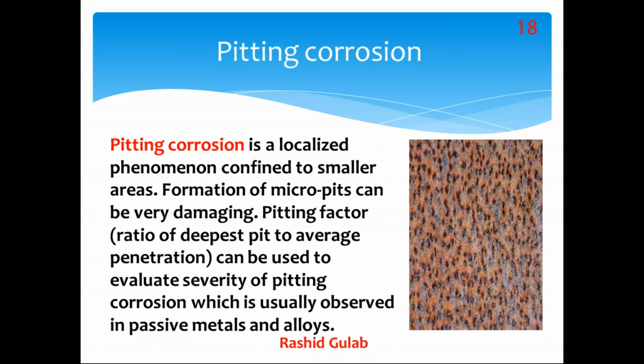Such kinds of pitting we can easily find after the blasting. When we are doing the blasting, after blasting, through visual inspection, only with the naked eye, without any inspection aids, we can identify this corrosion pitting on the surface. If we find any pitting after the blasting, we hold that pipe, we hold that structure for further investigation, and the further investigation is the NDT testing. And after the NDT test, if it is okay, then we proceed to the next step for the primer, intermediate, top coat, whatever we are going to do.